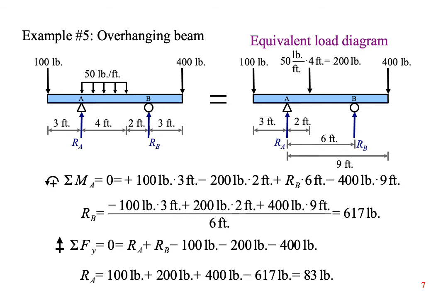If the supports are inboard of the ends of the beam, we call it an overhanging beam. This is how cars are made. The wheels aren't out at the bumpers. Instead, the car sticks out at the front and the back, beyond the wheels.